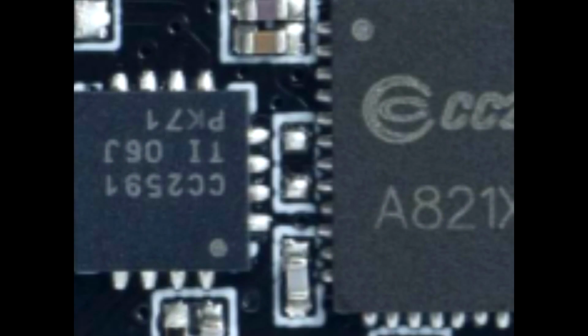And this gives you amplification, both transmit and receive amplification, integrated into one chip, which is pretty handy. And there is a differential interface that goes between the two. I don't have to worry about the impedance of that not being 50 ohm single-ended, because these two chips are designed to connect directly together. So I just put them really close together, run those two pins to each other, and they match. There is an unused pair of pads here where I could mount an inductor to repair the impedance match if it weren't good, but it's good because those chips are designed for each other.